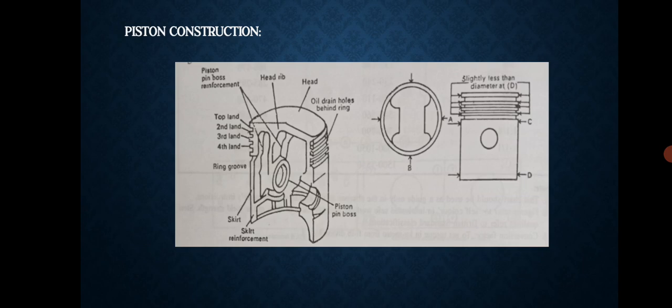The different shapes of the piston head allow for more or less compression and swirling as needed for the different engines and fuels. Diesel engine pistons may also have a combustion chamber recessed in the head.